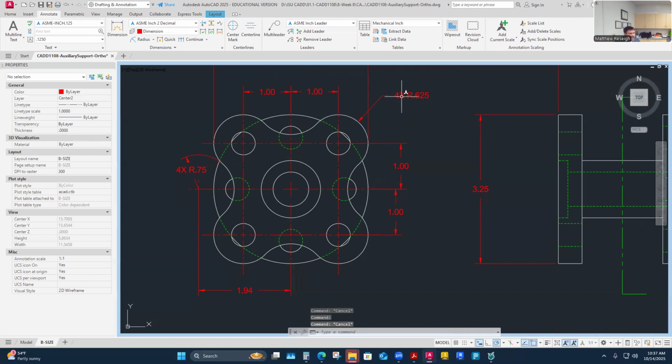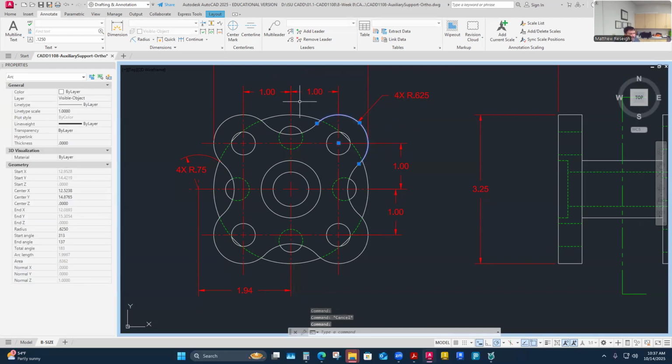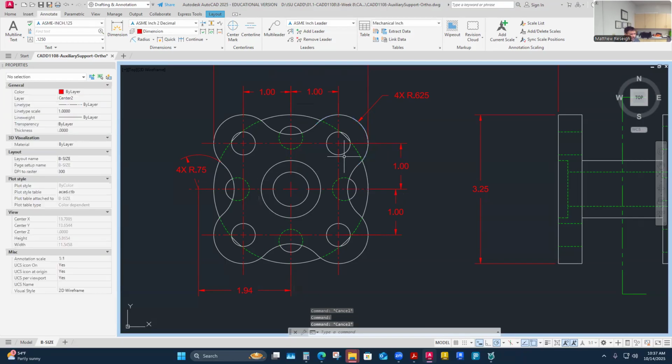And I don't have to take, I can say 4 times on that for size. I can say, and then these dimensions are pulling through with center lines, so I'm happy there. And so I've really sized and located the outer features of this, I feel like. I'm ready to look at the hole. The hole just needs sized and located. So the location's already done with the same radius, so it's just a matter of sizing one of these holes